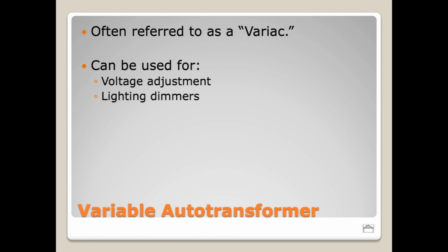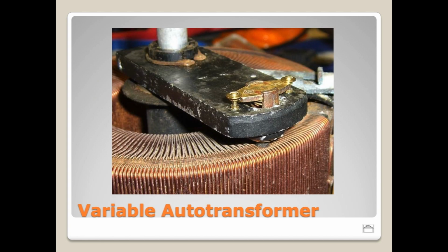All right, so if there is a piece of equipment that's in a similar state like that, where it's been sitting on a shelf for a long time, maybe a guitar amp as well, right? It's very common to, instead of just turning it on, put it on a variac. And as you adjust the brush up, you can bring the voltage up, the line voltage that's powering the device. And so you can go from 0 volts to 20 volts to 30 volts to 40 volts, all the way until you get to the full 120. So this gently brings the device back on and allows those capacitors to slowly wake up. How quickly do you do this?